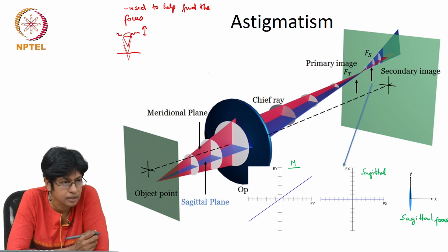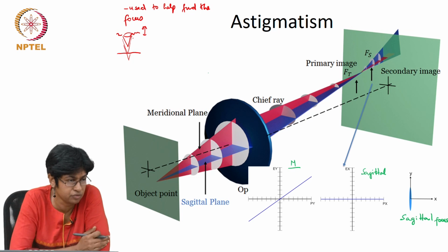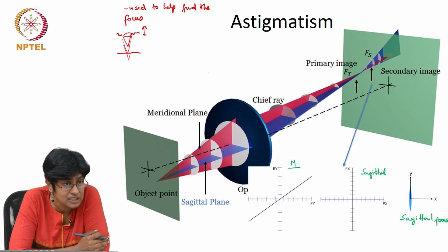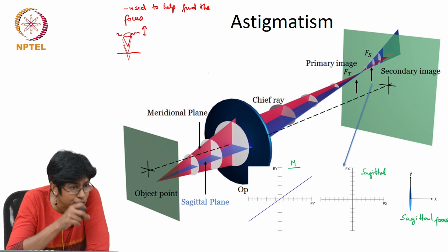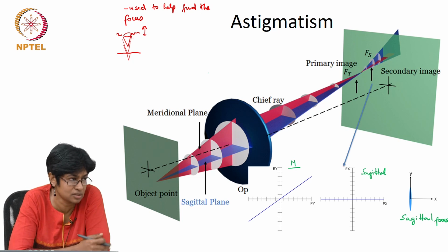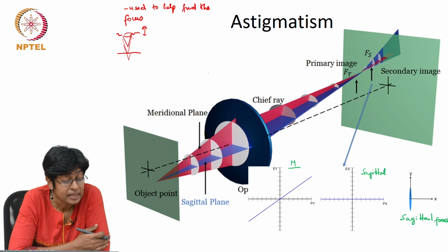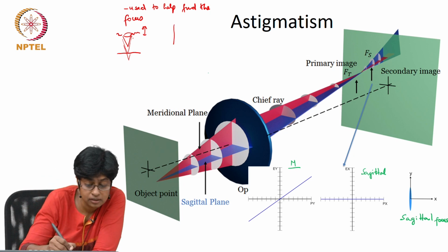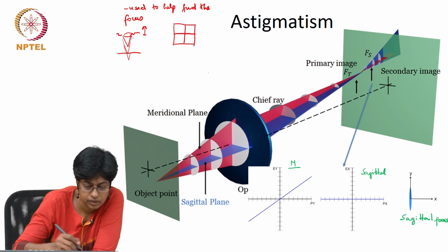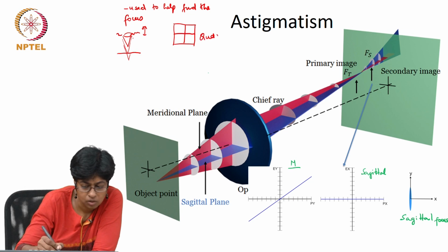So by moving the lens, you're changing where the focus happens. Okay. I want to adjust the height of the lens with respect to this surface such that the focused point lies on the surface. Now, how do I do that automatically? If I have a detector which has 4 quadrants, it's called a quadrant photodetector.